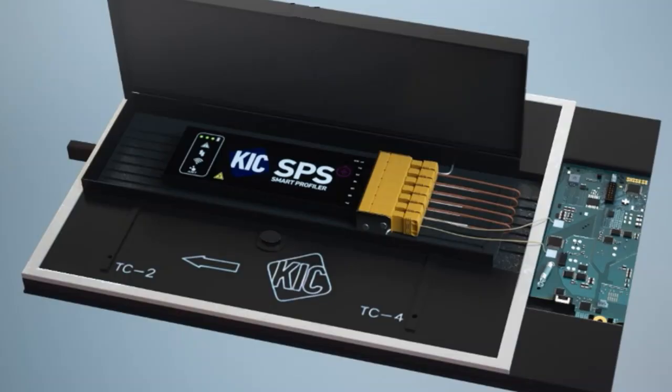Now, let's take a closer look at the Wave Surfer hardware. Wave Surfer is built on a Durastone pallet combined with titanium and stainless steel components. This construction makes the fixture durable enough for thousands of runs through a wave solder machine. Wave Surfer does not include a built-in profiler. This allows compatibility with 6, 7, 9, and 12-channel profilers.